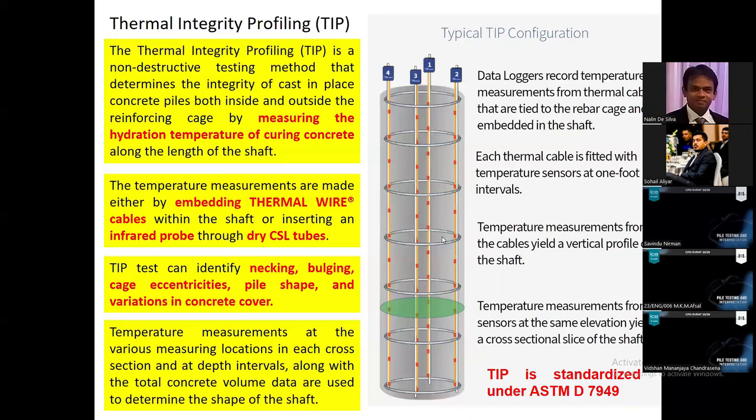So due to these issues, sometimes the cross-hole sonic logging test can create problems. Therefore, the thermal integrity profile test was developed to overcome these limitations. In the thermal integrity profiling test, commonly referred to as the TIP test, thermal wires are fixed to the rebar